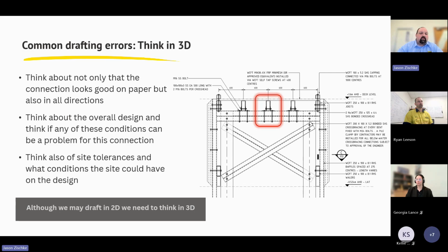Another thing is, where possible, you use the bracket only on one side. That makes it easier when piles are displaced from each other a little bit, or even at change of directions. Just on one side, a bolt and bracket from one bearer to one joist would standardize that whole connection, and take away from it being a specialized connection.